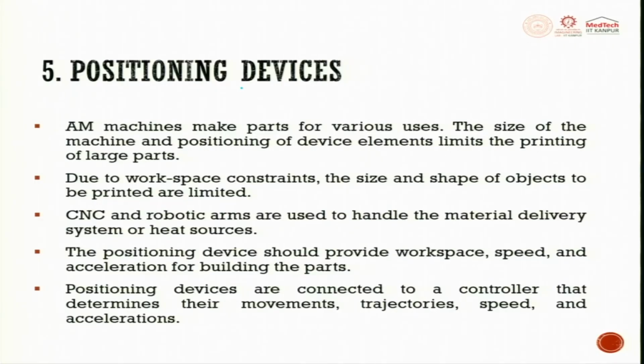The last part of our discussion with respect to different systems is going to be the positioning device. In additive manufacturing, machine makes parts for various uses. The size, shape and the machine all depend on the positioning. Positioning dictates the quality of the output. Due to workspace constraint, what is workspace constraint? This is a workspace, within which you start developing the output.